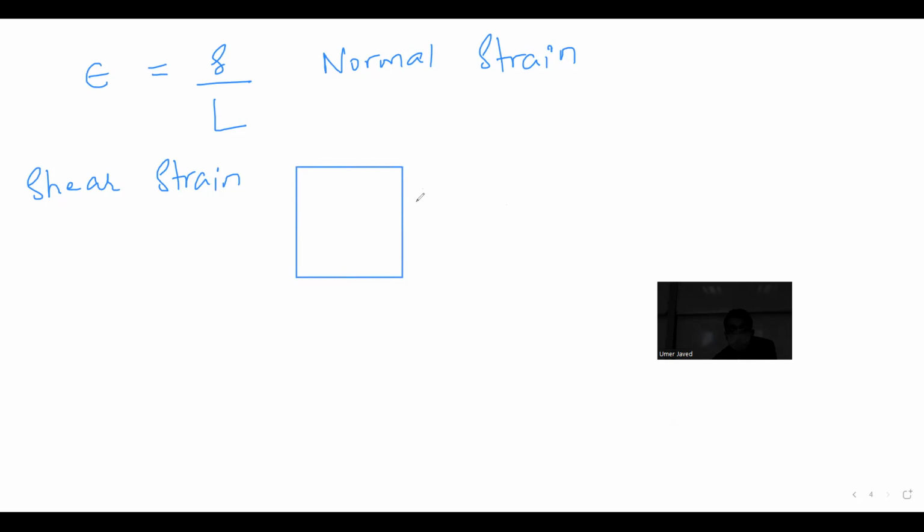What was the shape of our shear stresses? Anyone? There were arrows, right? Here, and then here, anti-clockwise, and then clockwise, and then clockwise. Or if someone does not like it, clockwise, this is anti. Now, for those of you wondering why shear stress this time has clockwise here and anti-clockwise here, and why just 10 seconds back the shear stress had anti-clockwise here and clockwise here?